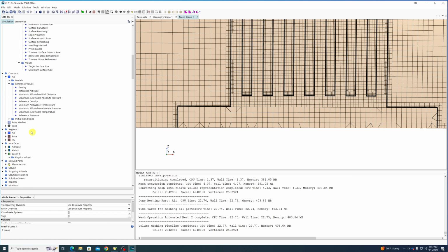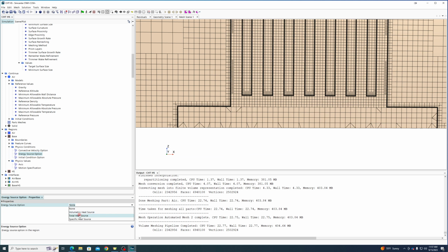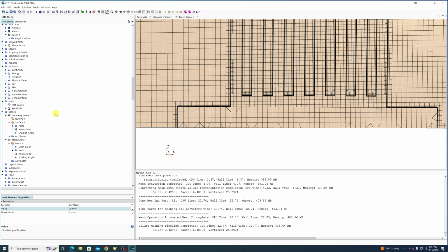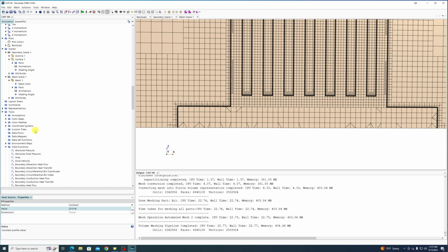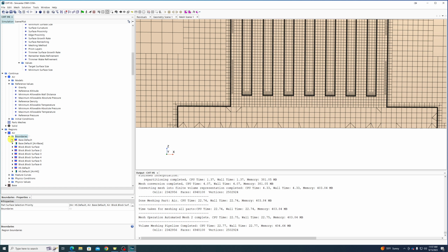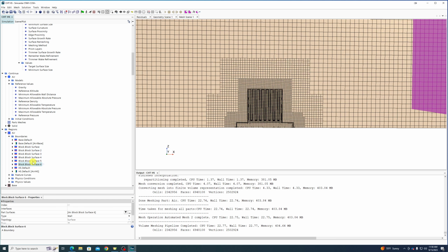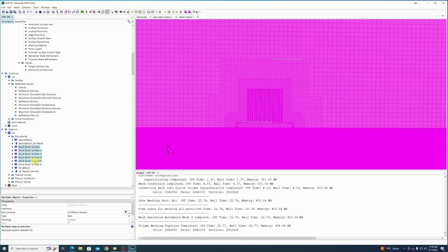So here's what we're going to try and do here. We're just going to more or less say this base plate is generating some amount of heat. It is a total heat source. We know the chip is generating, I don't know, let's say 25 watts of power. Let's go ahead and just see if we can get... Oh, we need to set the air boundary conditions. This is just going to be straight natural convection for the moment. Which one of these is the base? That's the base. Okay. So I really should have named these. I didn't, but we'll work around it.